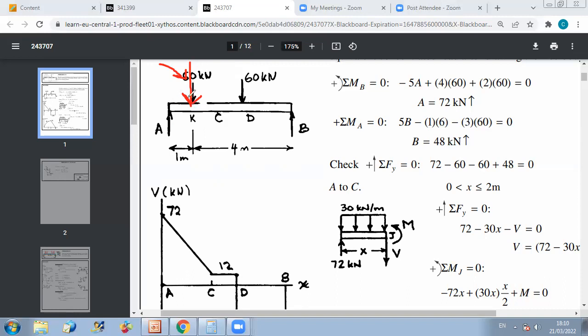And for example, if I'm doing a section after C and I want to do the analysis of internal forces between C and D, I can replace the distributed load here by one resultant force, because then it's similar to getting external reactions. Okay, because the section is not passing by this part, and I can say that the effect of this part on forces, when I study external forces and do sum of y equals 0, sum of moment equals 0 to find forces at this section, I can replace the distributed load by a concentrated force.